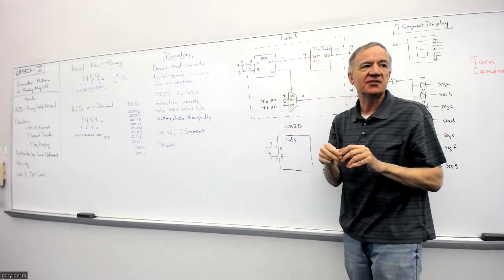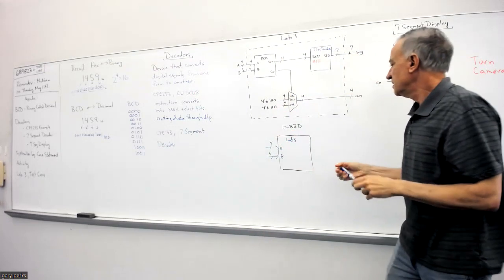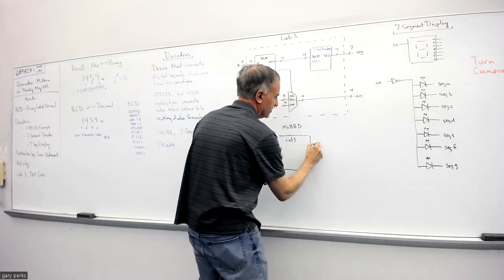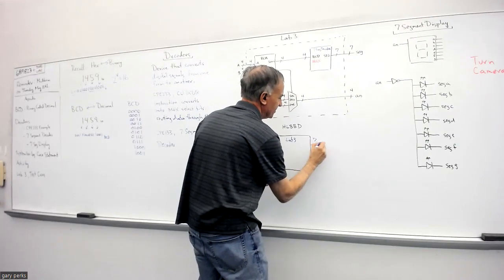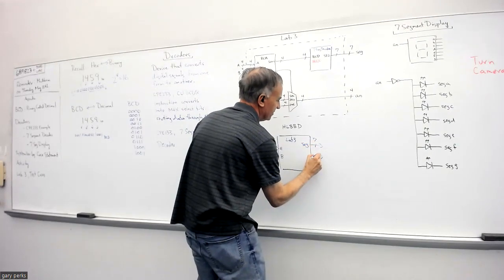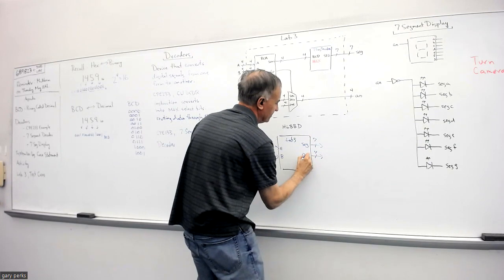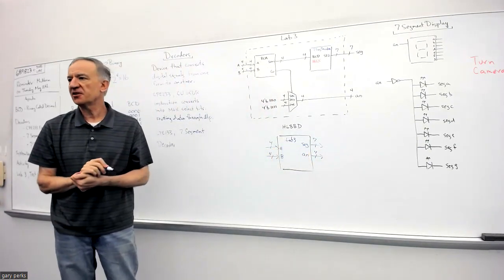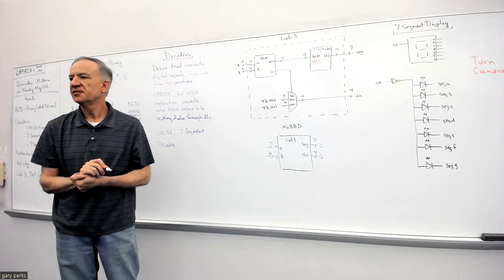That's what we mean by low level. Okay, so yeah, you're going to have 2 outputs. This is a 7-bit output, seg, and this is a 4-bit output, an. All right, so that's what your high-level black box diagram looks like for lab 3.